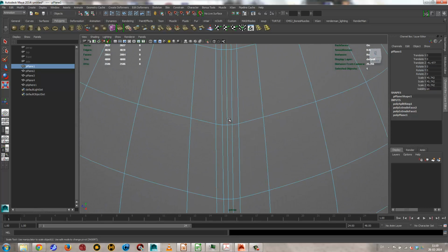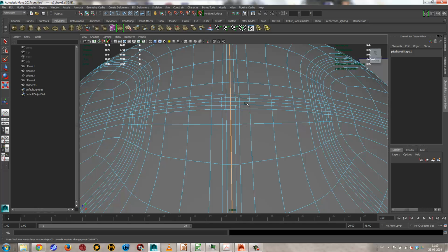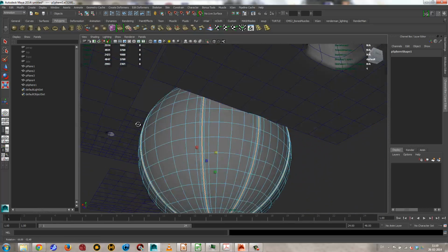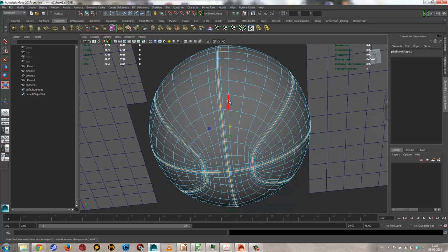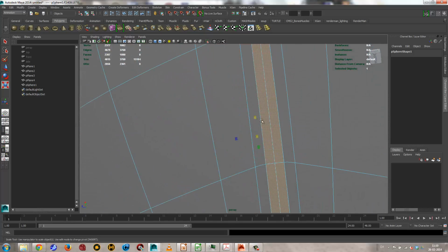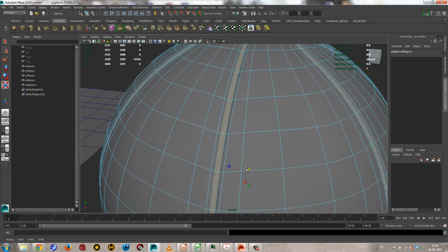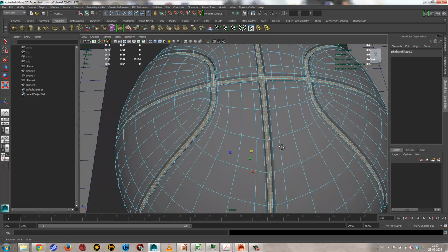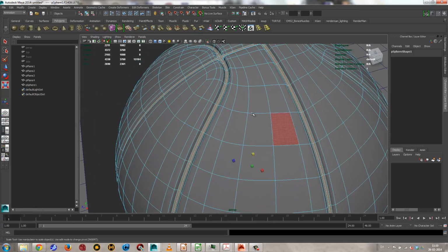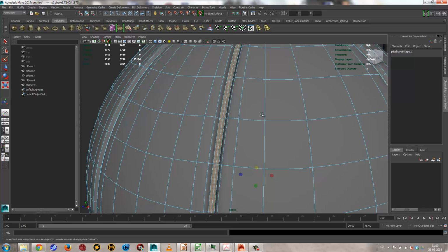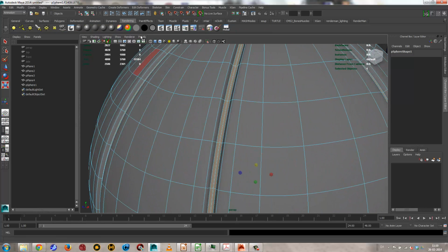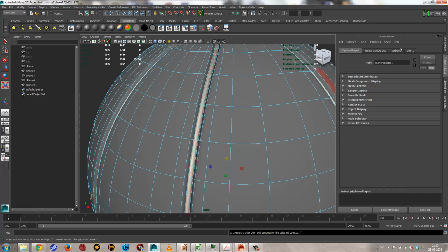And then I can go to edge and then grab these edge loops again. And that would be there, and it would be there. And then I'll use a little trick. Hold the control key, right click, say to faces, and that will convert my selection to the faces in here. And then I can do one or two things. I can scale these in to create this indentation for the basketball, or I could extrude them, but this looks fine. And then of course this I would add a different material for it. So this should be black.